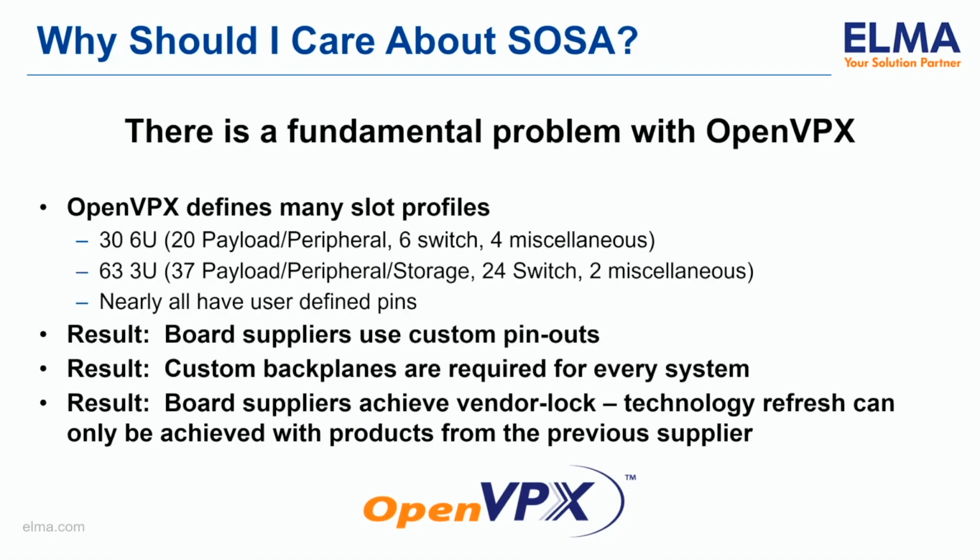Before I get into this slide, I'm going to say OpenVPX has been very good to me. I've been living in OpenVPX for 12 years now, I think. I was one of the co-chairs of the first version of OpenVPX, so it's very near and dear to me. But it has a fundamental problem. It has a lot of slot profiles. If I did my counts right, 36 6U profiles and 63 3U profiles. Now that's a mix of payloads and storage and peripheral and switches and other miscellaneous functions, but that's a lot.